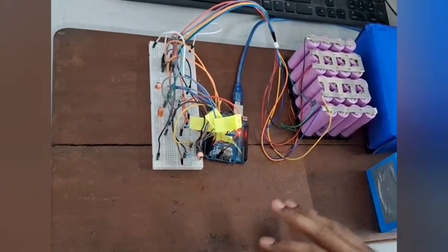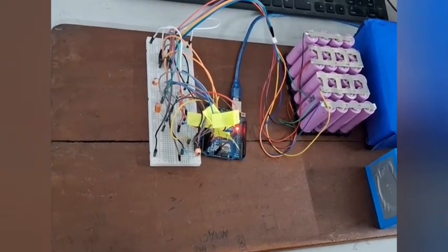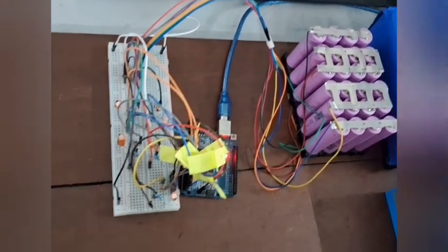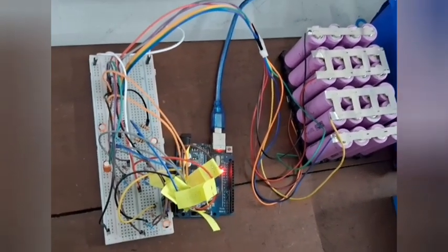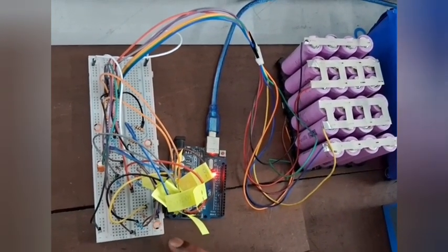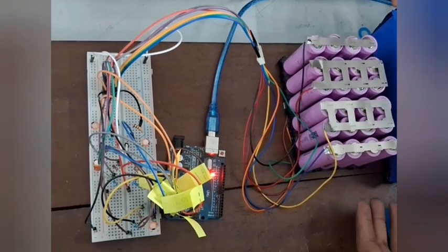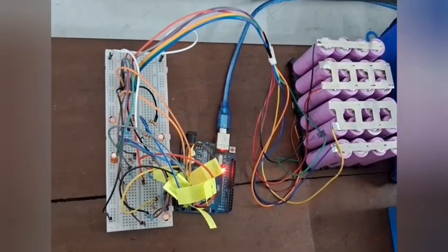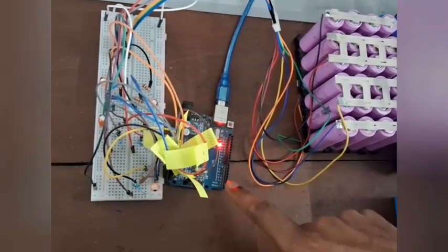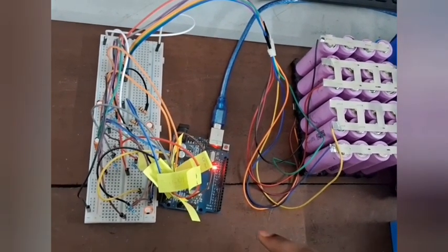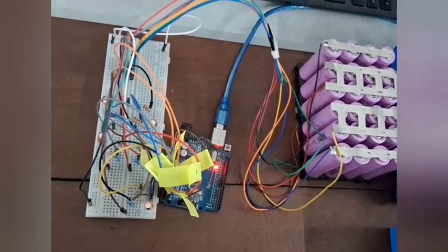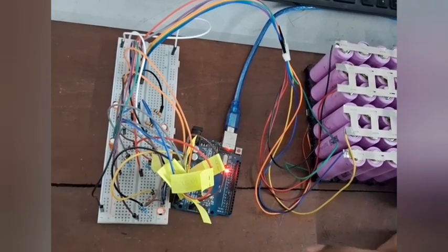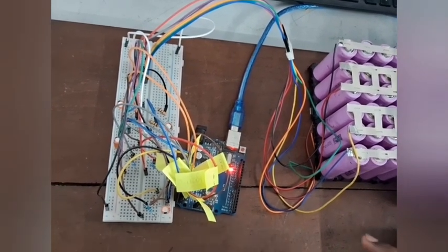We pretty much know that an Arduino microcontroller cannot handle voltages beyond 5 volt. So we have to maintain security at its analog pins. When we are extracting the strip voltage data from our battery pack, that is intentionally reduced below 5 volt and fed to our microcontroller. This microcontroller does contain our proposed algorithm, which is input in this. So this is our WAVES setup.